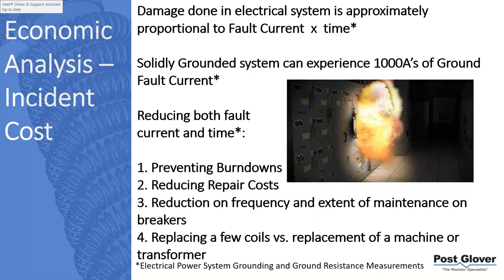But the point is this: IEEE talks about how at 10 amps or less, you can go as long as you'd like and you're not going to damage your equipment. That's not exactly true in terms of my first statement, although it's a good rule of thumb overall. For 10 amps or less, we're basically talking about zero additional damage. If you have a ground fault, something's happening, right? But you're not going to be stressing and hurting the rest of your system.